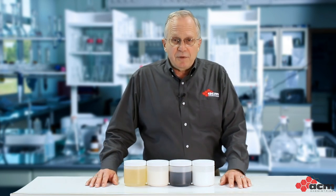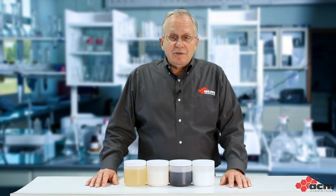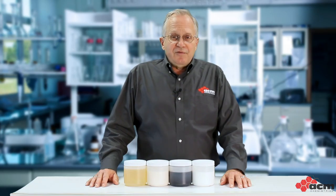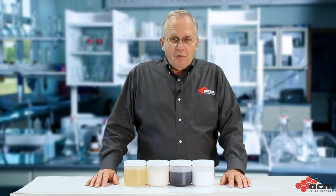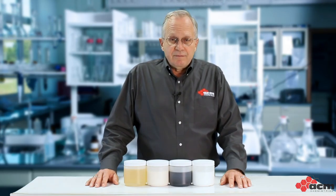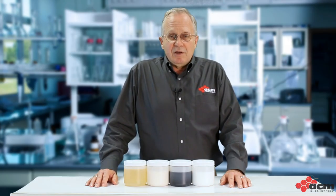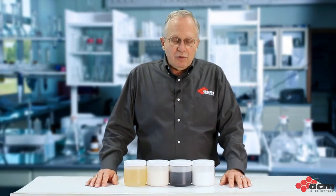Let's look at some examples of dry cast admixtures. There are plasticizers and densifiers that allow us to improve the quality of our concrete, helping it to flow and fill into the molds easier, improving the performance and appearance of our units, and reducing cost. There are retarders and accelerators. They help us control the speed of hydration of the cement, allowing us to make concrete products in both cold and hot weather.